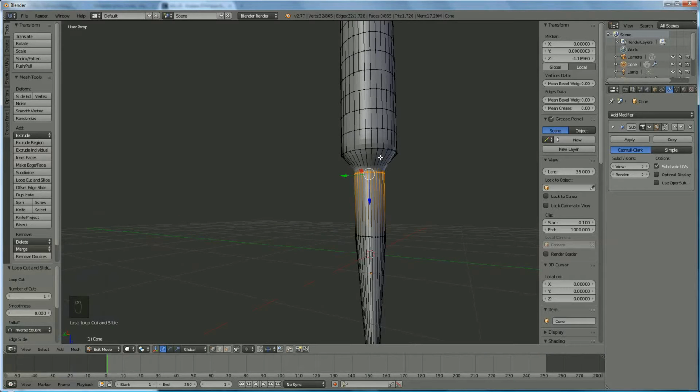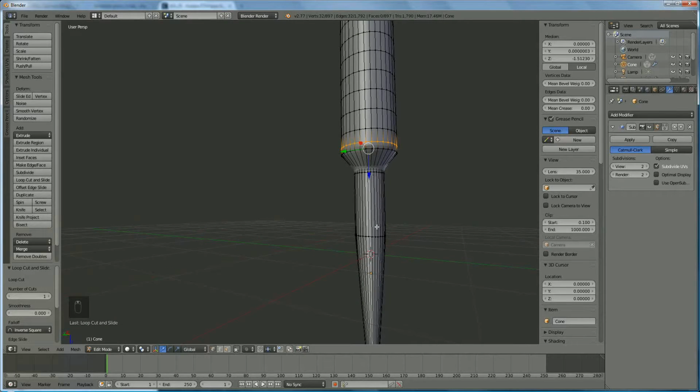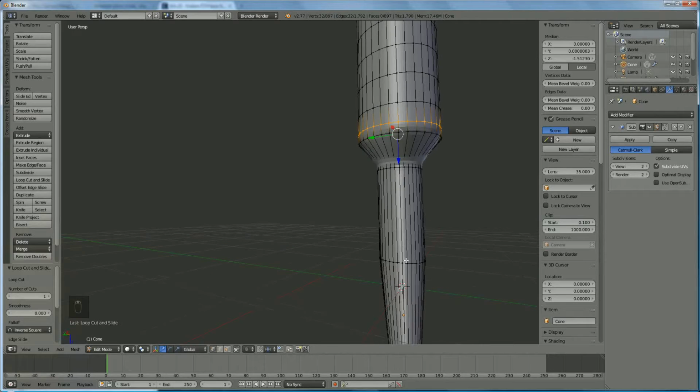So we add the purple line to the cylindrical part, and we're going to bring it until here. And this little round thing, we're going to make it a little better, so we press Ctrl R in the first part of that. Otherwise you're going to shape it not correctly. So if you bring it more down, the radius will be less. See? Okay, good.